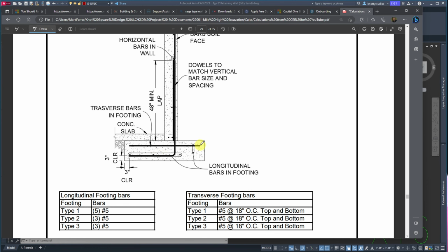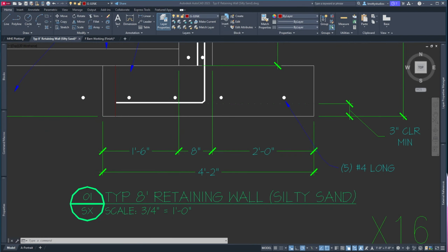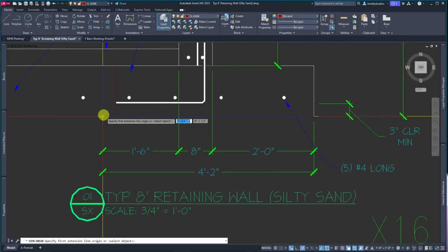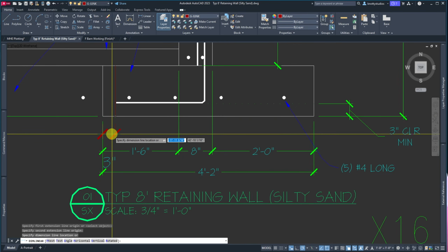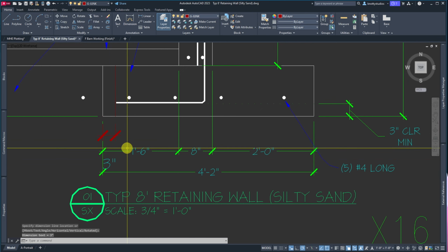So right now, let's put in this guy and then get the 3 inches clear. Here, I've got concrete up on top, but I don't have concrete over here. So if I set this at least 2 here. But to match what he's got going on, I'm going to do 3. And with 3, we got a whole foot of concrete to work with. So back into here, and we have our 3. And this could be dimensioned as a 3 as well. So if I just go dimension there to there, pull it down, that looks pretty good.